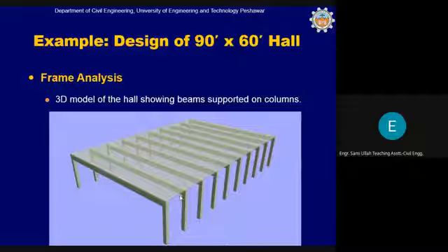And these beams and the slab both were supported on walls here. There was a continuous wall here, and a wall on this side as well. So this beam which we were designing was basically supported on both ends on walls. And that's why we call this a simply supported beam, and we analyze this using WL square by 8.